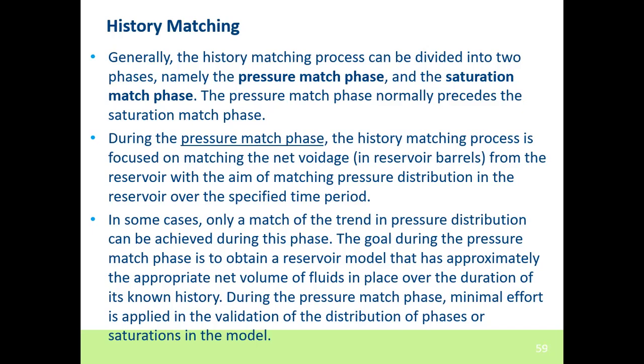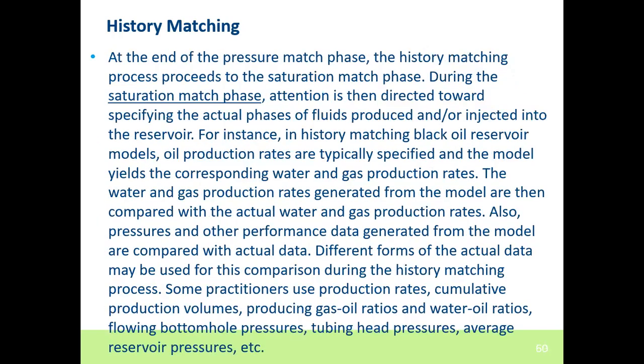The goal during the pressure match phase is to obtain a reservoir model that approximates the net volume of fluids in place during the duration of the history. During the pressure match phase, minimal effort is applied in validating the distribution of phases of saturation. So basically, we are looking at, for the underground withdrawal or the voidage, does my pressure match what I have? And you want to get a pressure match that is similar to what you have on the field.